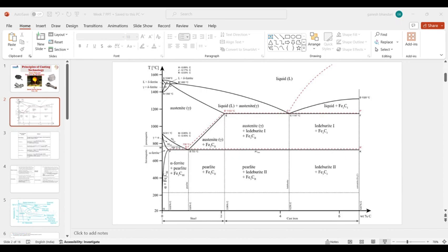But when we are going to put that sample in some application, we need homogeneous grains inside our sample. Okay, so after the casting process only, we can't go for application purposes of that cast material. We have to go for heat treatment process to refine our grains according to our need.